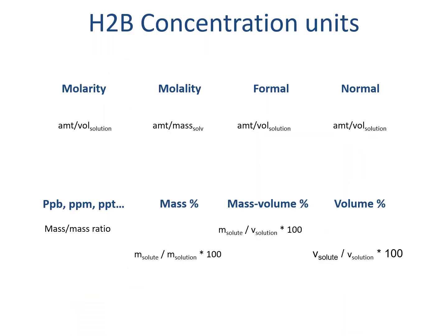So we care a lot about water, but we also care a lot about what's in water, and depending on what's in it, we may talk about concentrations a lot of different ways, depending on what we're measuring. The top 4 units are all based on mole units, an amount unit, and they're all particularly useful when an analyte, the thing that we're looking at, will undergo a chemical change. For example, it's helpful to know the molar concentration for carbon dioxide that's dissolved in water because it will be in equilibrium with carbonic acid. We always talk about those equilibriums on mole bases.